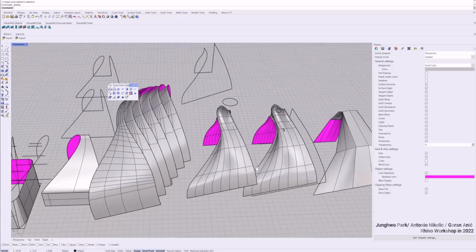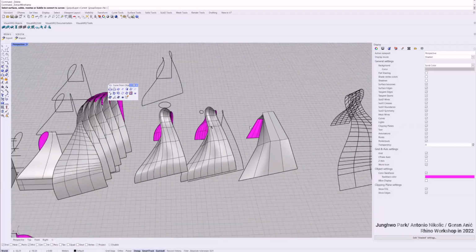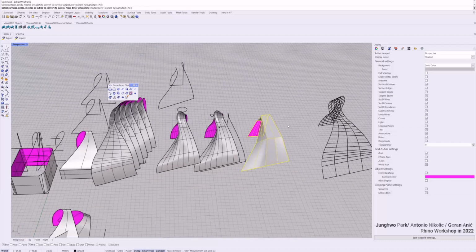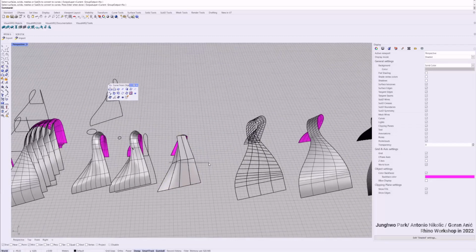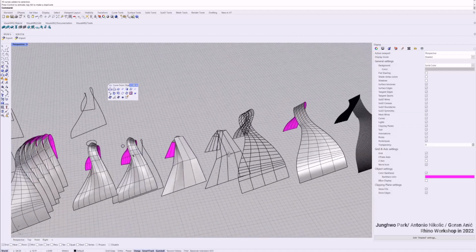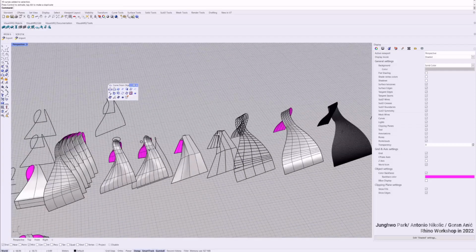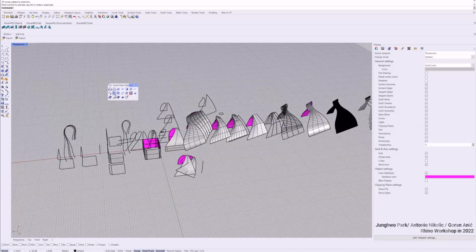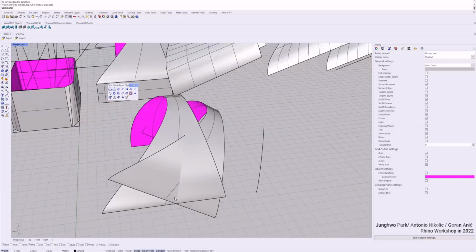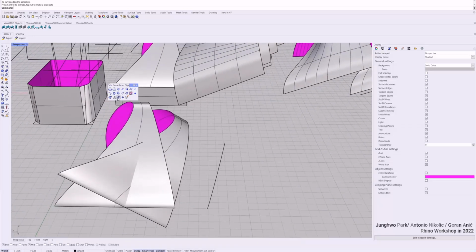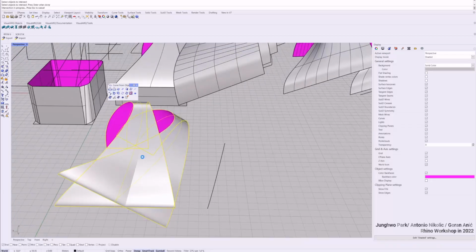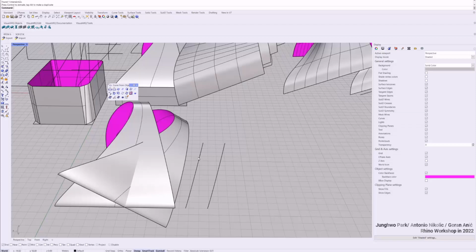Okay. And we did extract wireframe last time. When you select one of the surfaces, hit enter, then you can extract the wireframe of that. You see? We did it last week. So these Rhino commands are all very handy. Let's imagine you have this intersected surface and you want to get the intersection line of the two surfaces. Then you can use object intersection. Select objects to find intersection, hit enter, and you see this is the intersection line of both geometries.